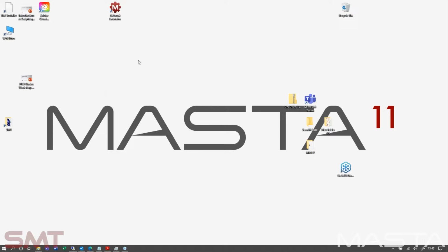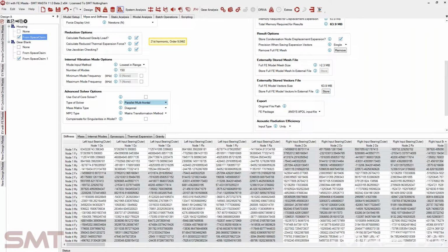Okay, so one of the questions that came in, I think there's quite a lot to do with the CAD Link capabilities. So I'll try and pick through a few of those. So does the CAD have to be a step, or can it be native Creo CAD? So it doesn't have to be a step file if you're importing it into Spaceclaim. So obviously a lot of this relies on Spaceclaim, because that's what our link is primarily with. But you can open files from those other CAD packages in Spaceclaim fairly effectively.